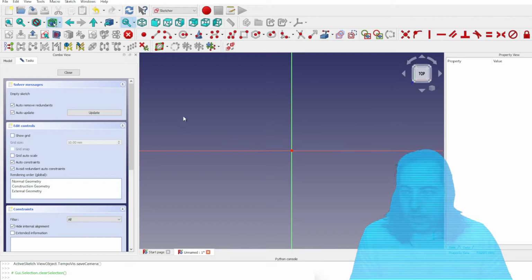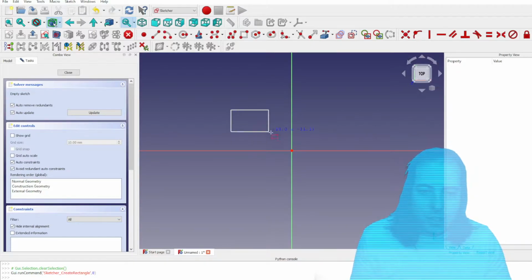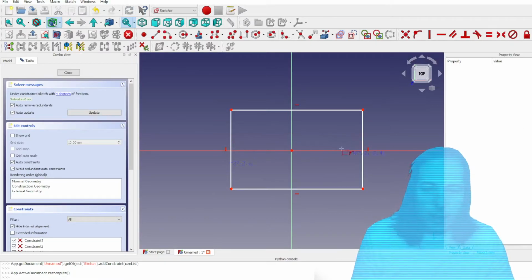All right, so I clicked OK, and now we have the center, and you'll see up here in the top right, it says top. Here's where we can start making a sketch. And if we wanted to make an oval design, we'd use one of these. We can make more of a rectangular design. There's a circular design if you want to make a tube or something like that. So it's good to be familiar with what you have available. So let's go ahead and use the basic rectangular sketch. So I click on it and I just give, roughly over top of this here, and I click again, and then we have a rectangle.